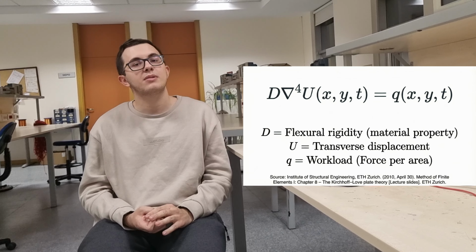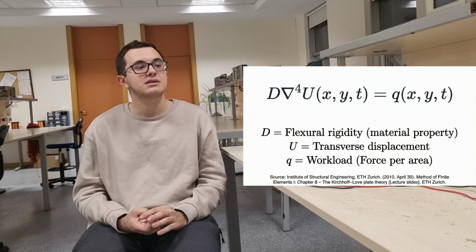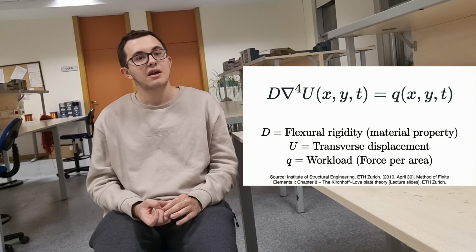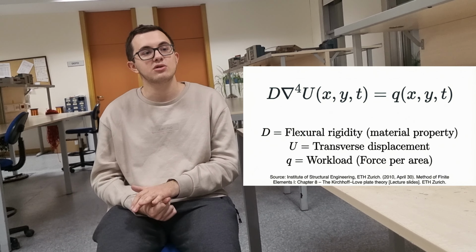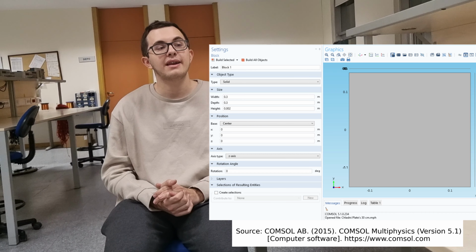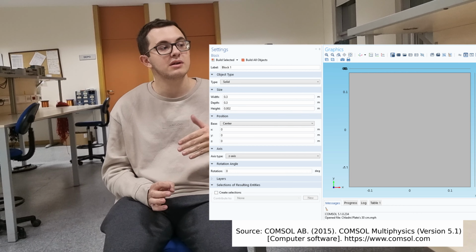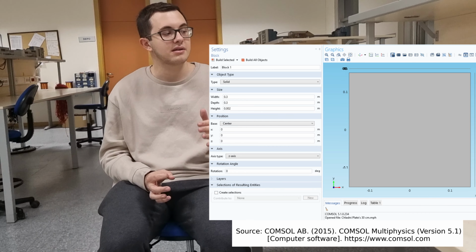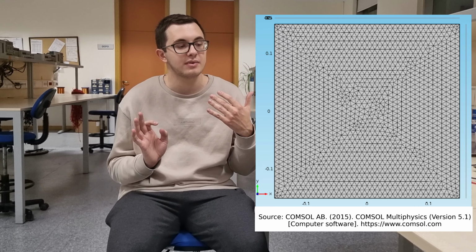This is a fourth order biharmonic equation. Because it's fourth order, its analytical solutions are limited, and due to the lack of analytical solutions, we will use simulation tools like COMSOL to solve this equation and look for the solutions. COMSOL uses the finite element method to create a digital copy of the material and the plate setup, dividing it into small triangles, and then applying the correct boundary conditions to solve the equation.